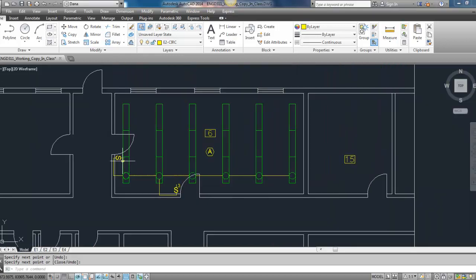And so now I have my three-way switches. The switching will actually go through the conduit into the luminaires from one switch to the other, and then it'll control all these lights at the same time. So when somebody walks into this room and turns on this switch, all of the lights come on at the same time. And if somebody were to exit using this door, they could turn all the lights off using the switch. So they all have to be connected through the junction boxes for those luminaires.